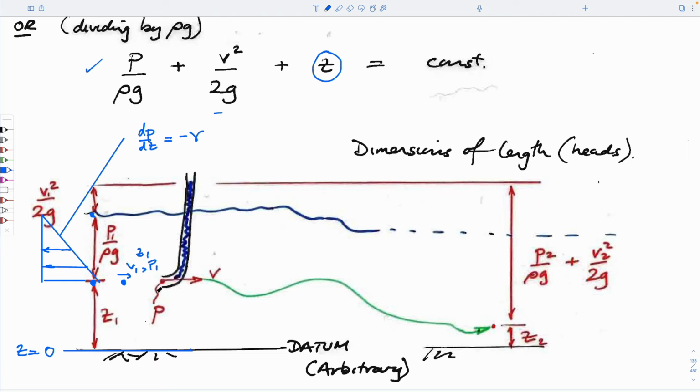If you look on the plane as you get onto a small commuter plane, you'll see this little right-angled thing jutting out of the side of the cockpit, and it is exactly this. It points in the direction that you fly, which is usually forwards. It means that there's a stagnation point here, which means that the air velocity is killed by the stagnant fluid inside this tube.